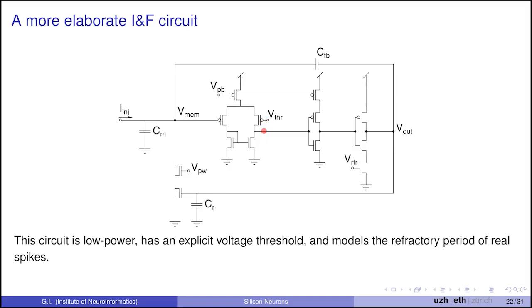So you have here a high gain stage, which takes slow changes in the input and makes fast changes in the output. If you have fast changes here, then having an inverter is not a problem. And then the second inverter never was a problem because the output of the first inverter also is making very fast changes. So the only problem was with the input to the first inverter, but if we have an amplification stage at the beginning that makes the changes fast, then we solve that problem.